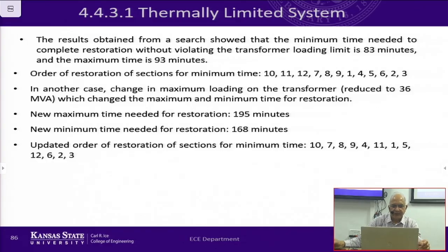And then we said, okay, let's change the loading of the transformer, the maximum loaded from 45 to 36. In this case, you have to wait longer because now we have to reduce the number of sections that can be restored in the beginning.